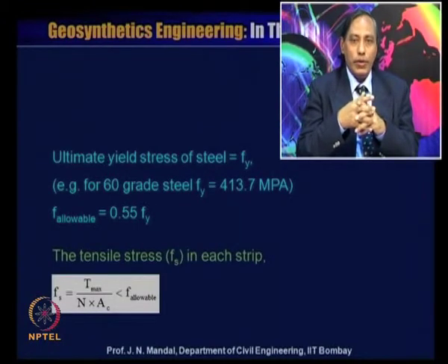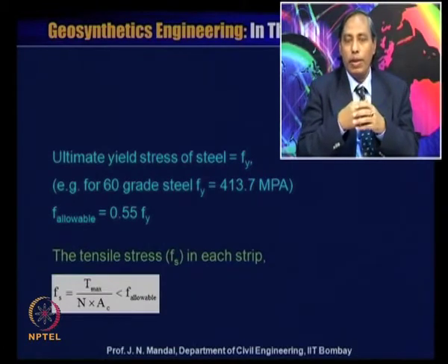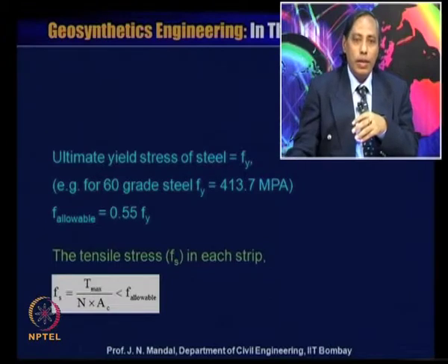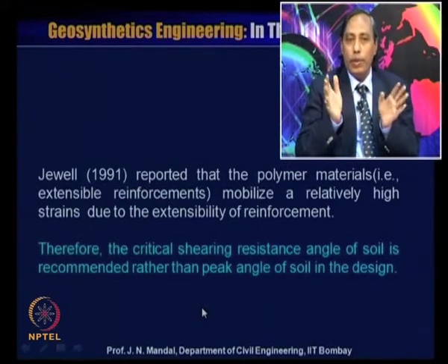So the tensile stress Fs in each strip can be calculated with this equation: Fs is equal to T of maximum divided by N times AC, and this value should be less than the F allowable value. If it is less, then it is okay.